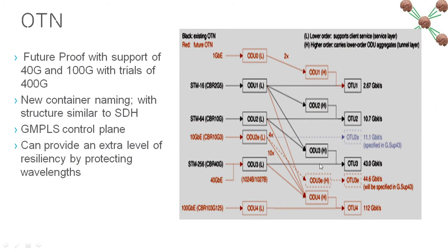The good thing about OTN is that you have a lot of new features, for example the GMPLS control plane, so you can very easily put the network to run on its own. It will find all the bandwidth limitations and distribute the traffic so that it goes in the best possible way through the network. Your network will always be well optimized, well maintained if you let it run on its own.